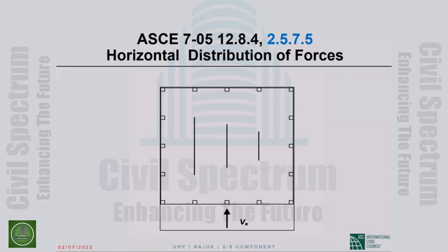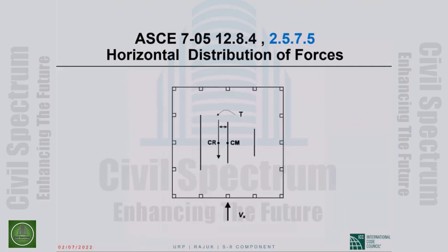If it deflects a lot, it's a flexible diaphragm. Okay, so if the diaphragm is rigid, which should be most of the time the case, the lateral force distribution will be as I indicated. If, on the other hand, the diaphragm is flexible, then the story shear is distributed to the lateral force resisting systems in proportion to the tributary areas, not the relative lateral rigidities.